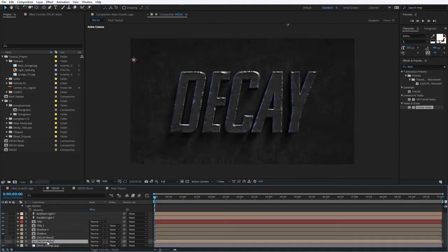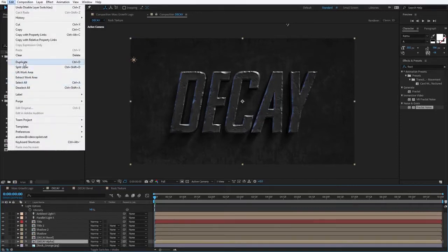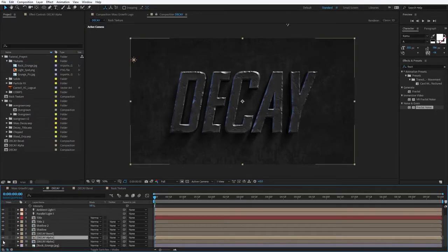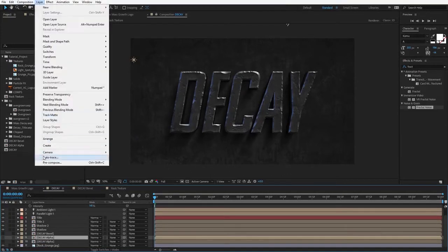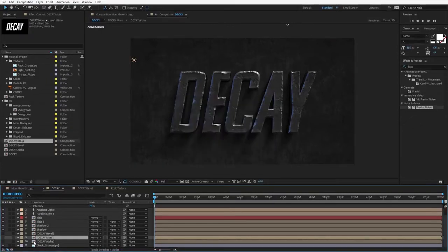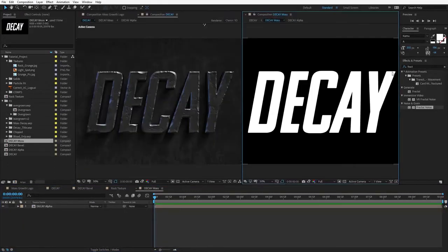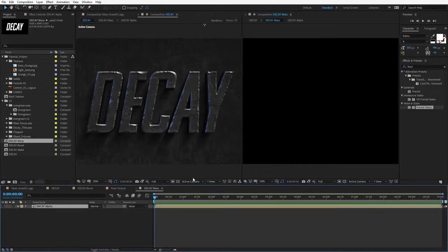So first thing we'll do is we'll take a copy of the decay alpha, and we'll choose Edit, Duplicate, and we'll turn it off, and then we'll take the copy here, and we'll choose Layer, Precompose. We'll move all the attributes, and we'll call this Decay Moss. And then we'll hit OK. Now, we'll double-click on the Decay Moss, and let's move it over to the side here. And I actually just want to turn the alpha channel off. We'll probably use it later on.